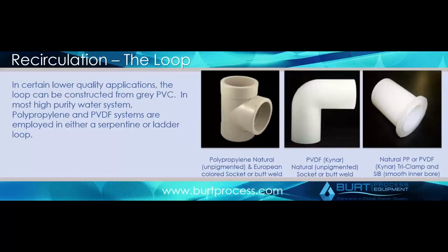And choosing this material is really a choice between the economics of the system, since loops can be very large, 600, 700, 800 feet, and also maintaining the water quality that's involved with it. If you're in the pharmaceutical industry, you're going to be almost exclusively a stainless steel based system because of the steaming and the bacteria requirements. Although they do make thermoplastic, they do see thermoplastic sanitary now.